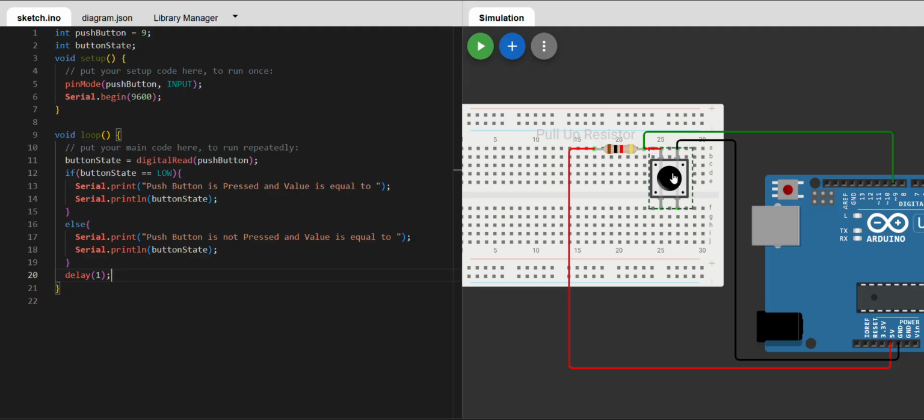It means low. When you push the button, you are getting the output low, so that it is called the active low condition or the active low configuration. Whereas why this particular resistor is called a pull up resistor: when it is in the off state we are getting the 5 volt supply or the high, so the resistor is treated as the pull up resistor. Why? Because it is pulling up the voltage value to 5 volts.